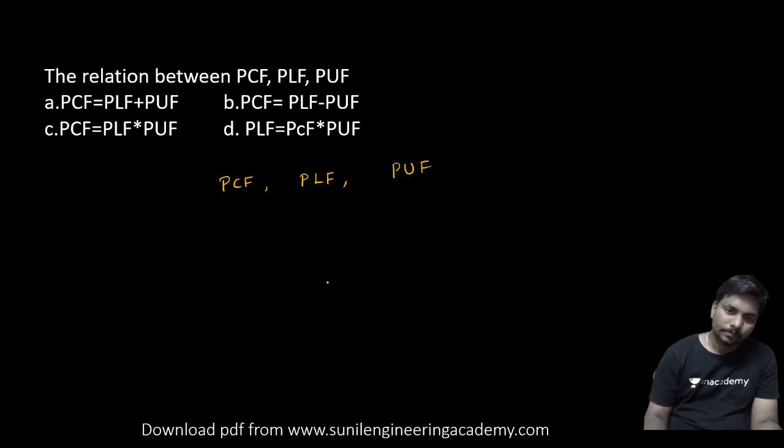Let us take plant load factor is equal to average load by maximum load. Plant capacity factor is equal to average load by installed capacity.